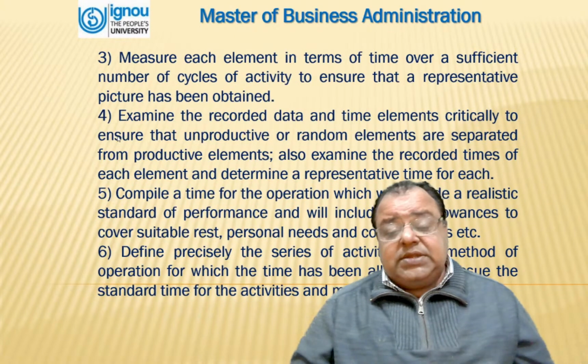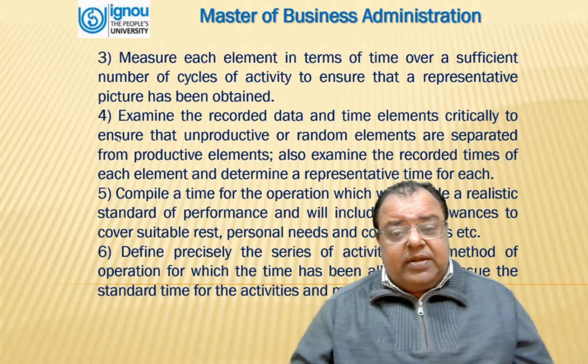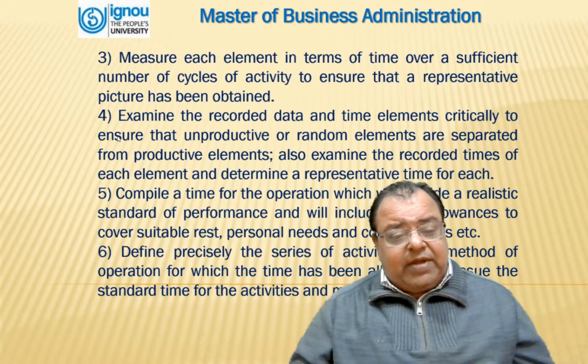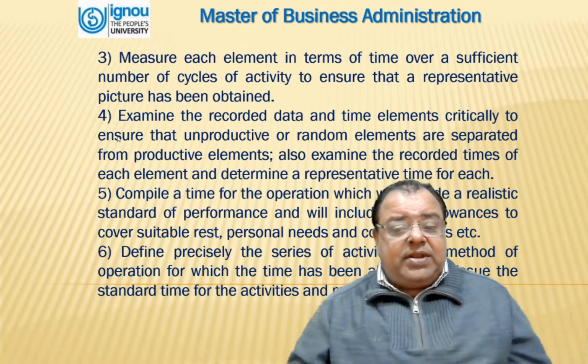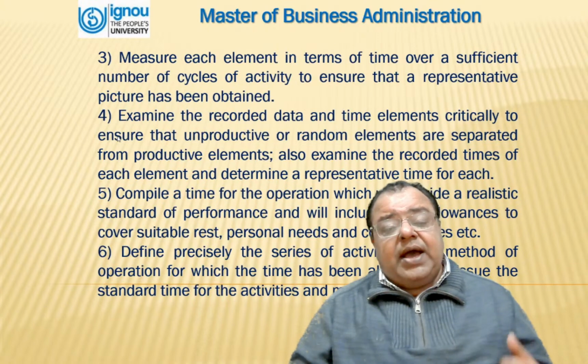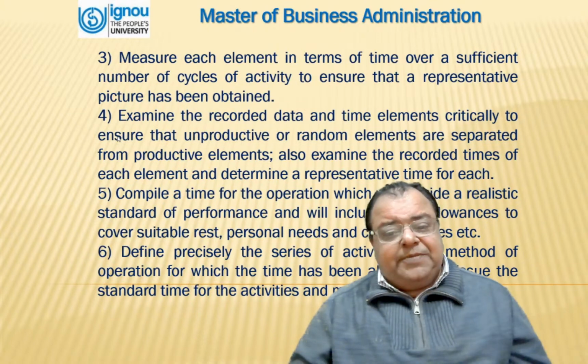Fourth, examine the recorded data and time elements critically to ensure that unproductive or random elements are separated from productive elements. Also examine the recorded times of each element and determine a representative time for each.